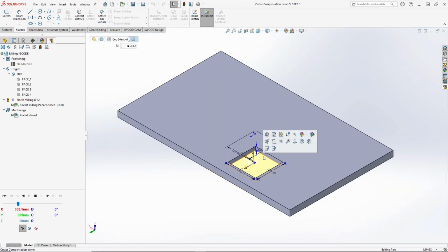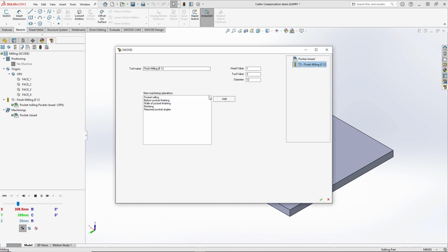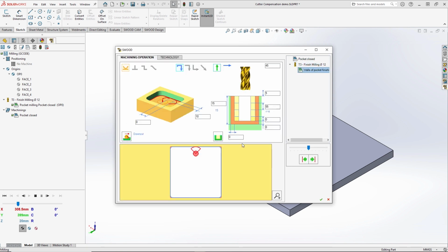Users will usually apply cutter compensation when applying a wall pocket feature, as this feature focuses on the pocket's outer bounds and is therefore necessary in this scenario.